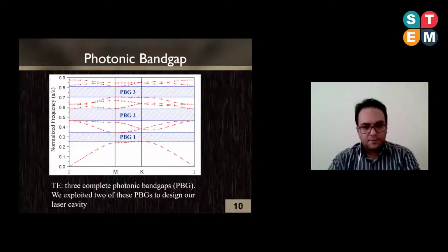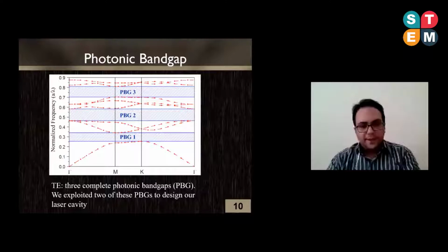We know that telecom C-band indium arsenide quantum dots with a medium density are grown within indium phosphide membranes, and our proposed slab is about 6 periods across by 7 periods long, making a miniaturized device about 3 microns in width and length.